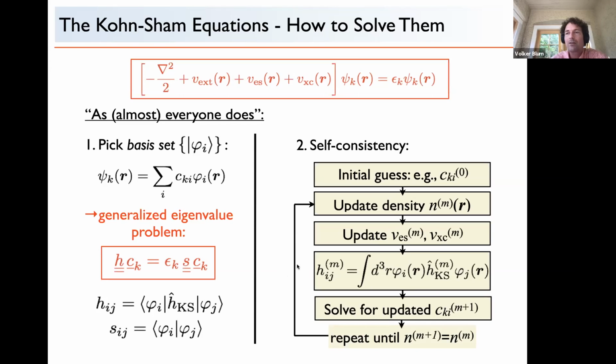We put these back in to build a new density. In here, we actually make sure that we keep the iterative process stable. This is known as mixing. And you'll see that in FHI-aims somewhere written out that we're doing mixing, and you can actually play with the parameters if you like, although the defaults that we provide should hopefully be sensible for a wide variety of calculations. And then you iterate this process to convergence until you really have a solution that yields the same Hamiltonian as input, which produces that solution as output.